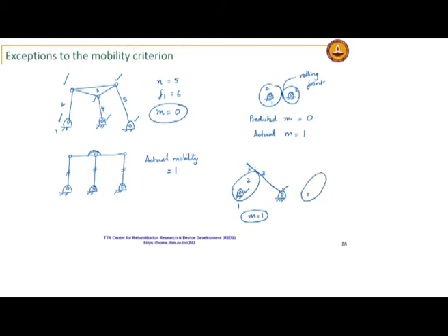So, I do not want too much wear on just one part of this follower. Okay. So, I modify that to say that I am going to have a roller here instead of just this link directly in contact with the cam, okay, because the roller will keep spinning and I will have different points of contact. So, practically that is a better way to handle wear.